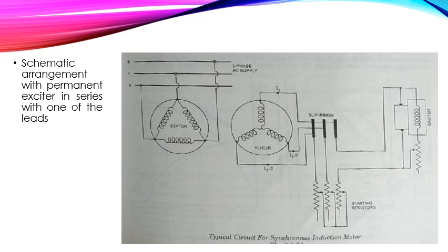So the interesting point about this motor is that its peak torque as an induction motor exceeds that as a synchronous motor. So if it is momentarily overloaded as a synchronous motor, it may continue to operate as an induction motor with considerable pulsations of current and torque due to DC until the load falls and it is able to resynchronize.